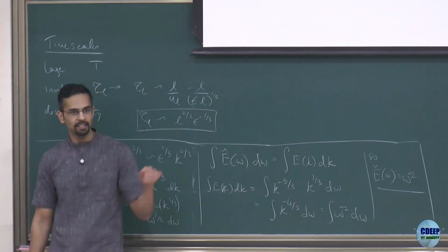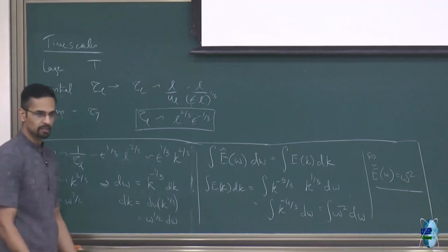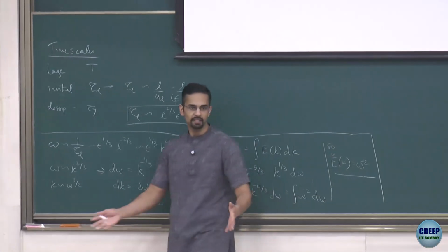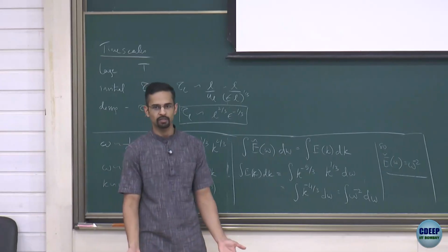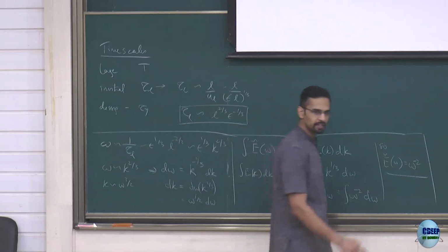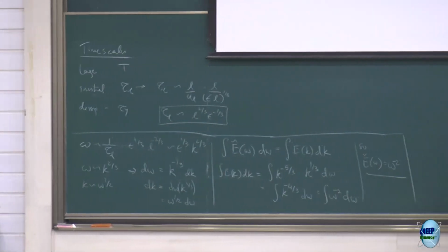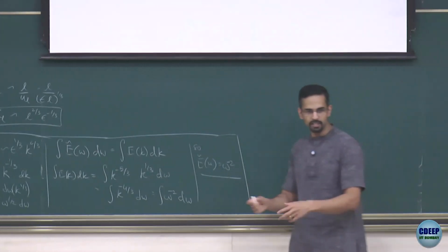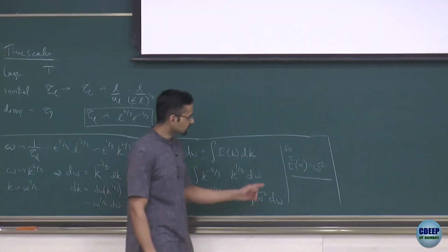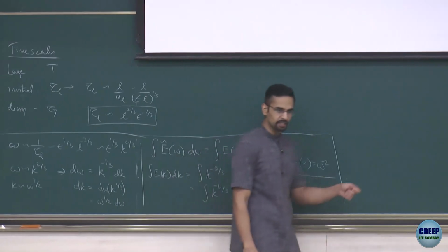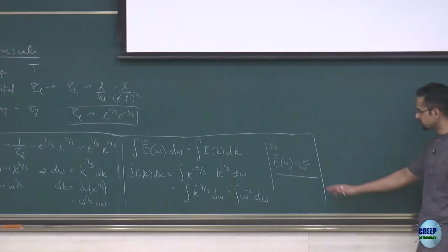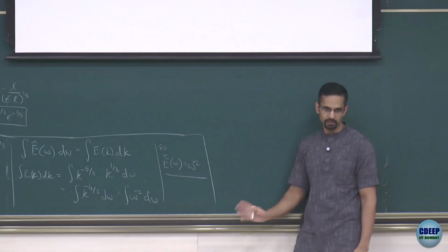So this means again that the power spectra will be such that there are more slow frequencies and fewer high frequencies. That's the same as saying the amount of energy content in smaller and smaller scales should decrease. Otherwise, my flow will have huge gradients. It doesn't make sense. For any flow field to be differentiable, or at least so that the flow doesn't blow up, the smaller scales should not have all the energy content. It has to smoothen out as you take smaller and smaller scales. Here it is the same thing in time, so that my temporal signal will also be differentiable if I zoom into small enough times. And that requires this to decrease and eventually cut off and become smooth.